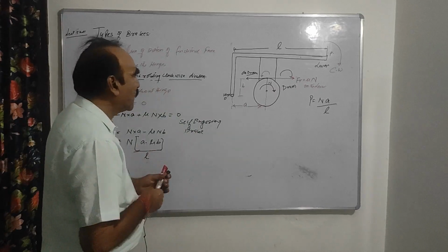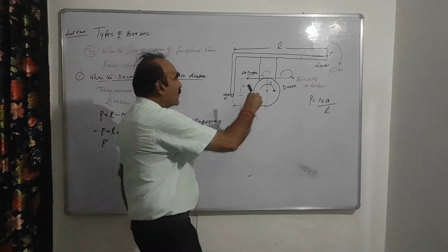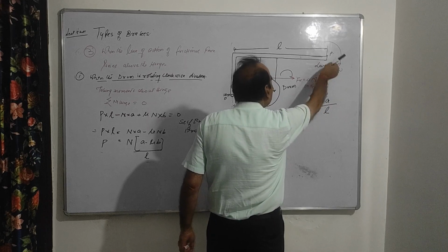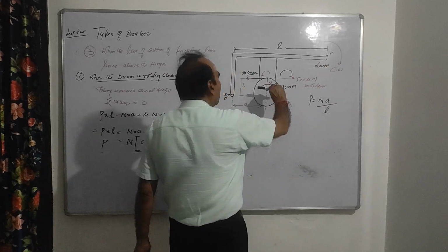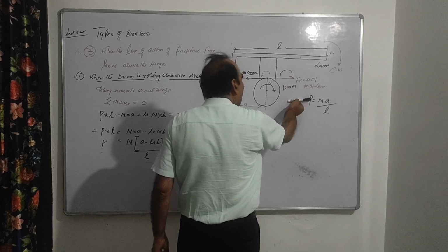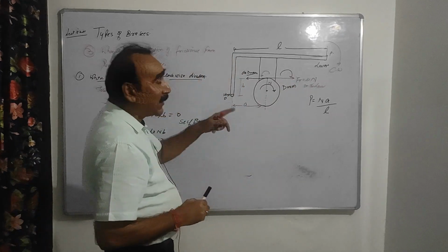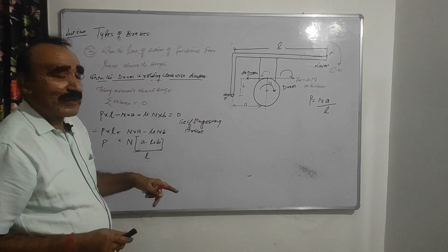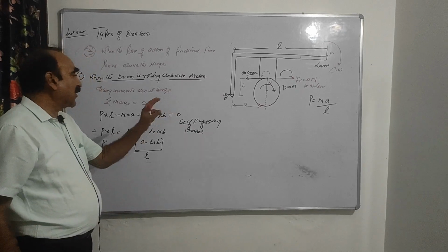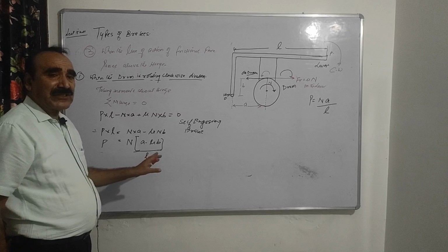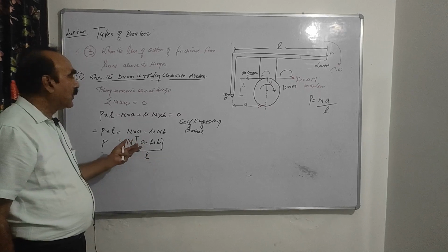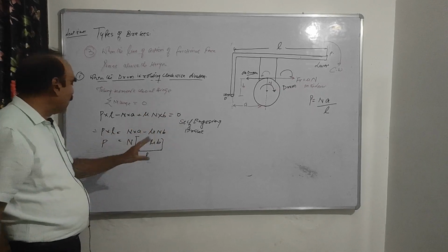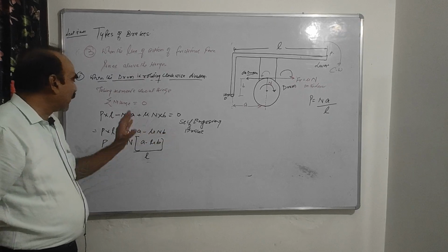And as I told you, here also the moment of P is in the clockwise direction. And the moment of Ft is also in the clockwise direction. When the moment of P and the moment of Ft are both in the same direction, then you can say your brake is a self-energizing brake. The rest of the conditions I have already explained in the previous topic, all the conditions are the same.